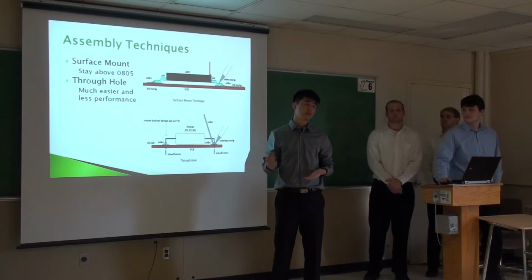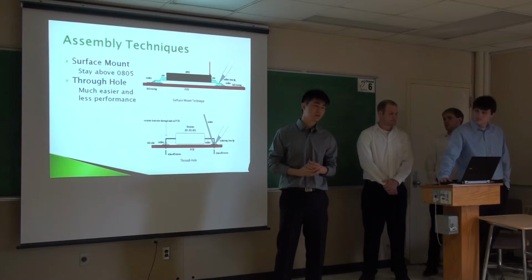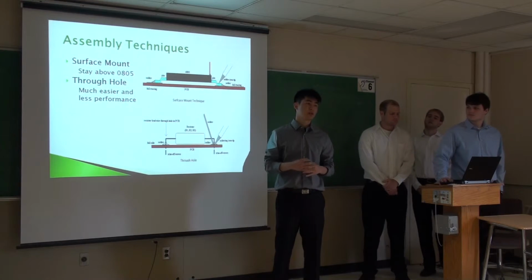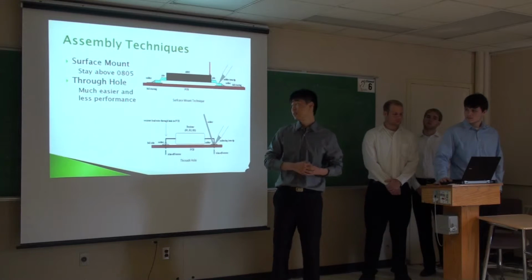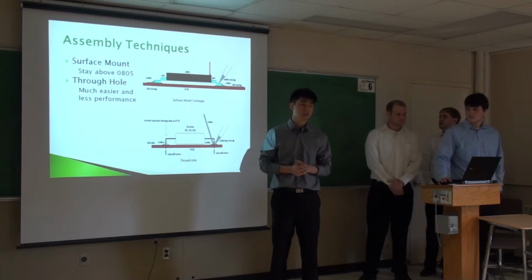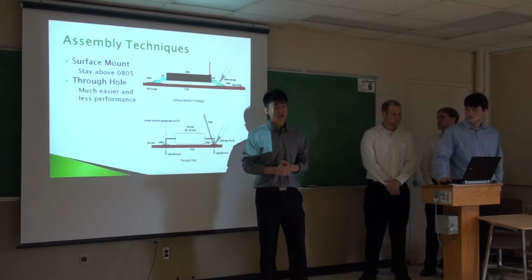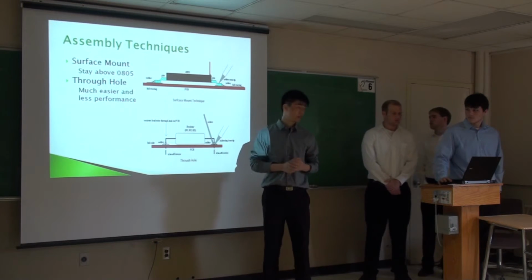So the components are placed through the holes or vias of the PCBs, and then the vias will be filled with solder either on the front or back side of the PCBs. So hand soldering is cheap, but it imposes placement limits. So the component package needs to be, say, above 8 times 5 mils.